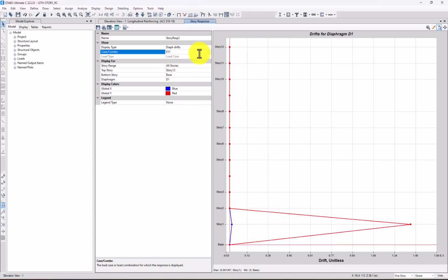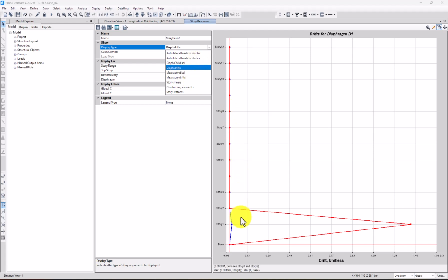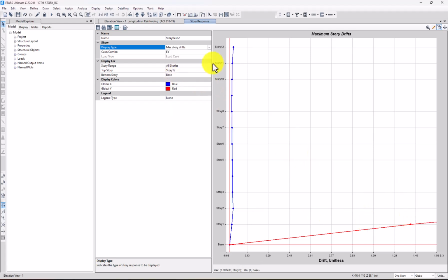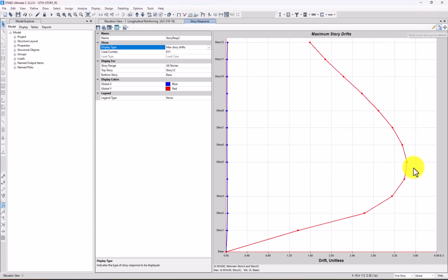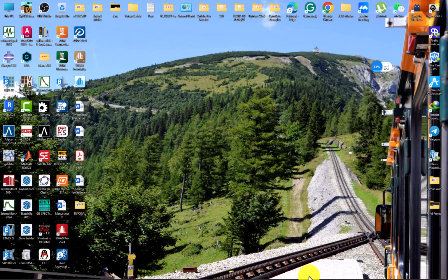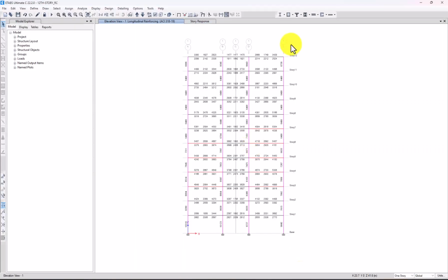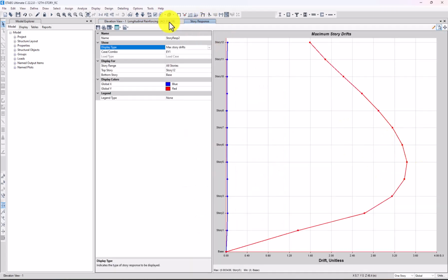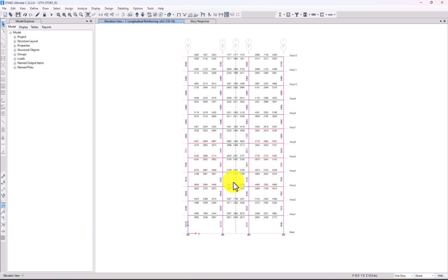So we have only one diaphragm here, so we must give the diaphragm to all structure, then we can come to here. So we come here, and in this story, between story 2, 3, 5, there is a quite large drift. So in this case, the structure didn't pass, especially the beams, because that large drift caused to generate some torsion here, but the drift is passed.